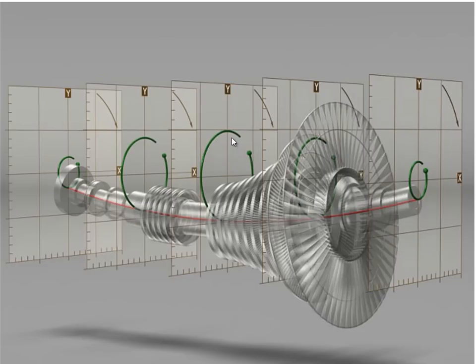Now we may not be able to put proximity probes in all these locations. I'm just showing this for illustrative purposes, but this is the orbit, and that orbit tells us, it may be small and circular, that's good. It may be bigger and elliptical, and then we have to start to ask, well, is that okay? Could it mean there's some preload or misalignment? If it gets big, then it could be the oil whirl we just looked at, or oil whip.